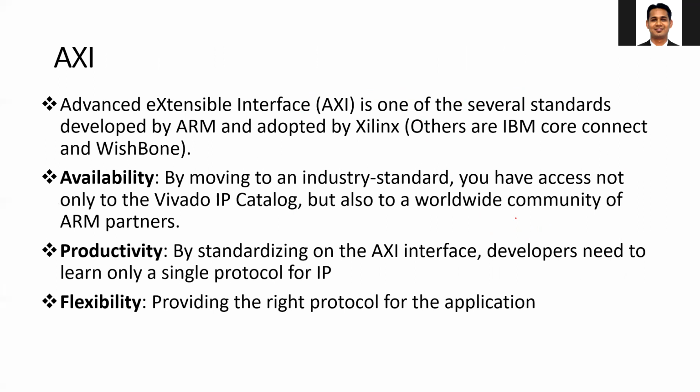AXI stands for Advanced eXtensible Interface. It is one of the several protocols we have discussed. Why are we using it? Because our hardware, which consists of the ARM processor and the FPGA, uses the AXI protocols.